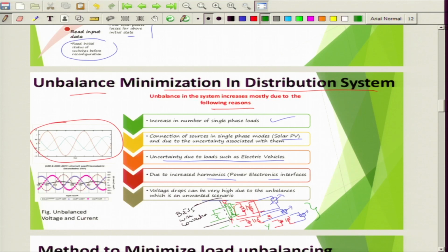On the other hand, the other option could be, if you want to control on the other side, where the batteries are connected to B and Y phase, you can try to increase the discharging of these batteries, so that you reduce the burden on the transformer, and the R, Y, B phases from the transformer perspective do not seem to be overloaded. So one can think in any direction based on the placement of the battery on the primary or secondary side. One can look at various options to try to reduce the unbalance in the system.